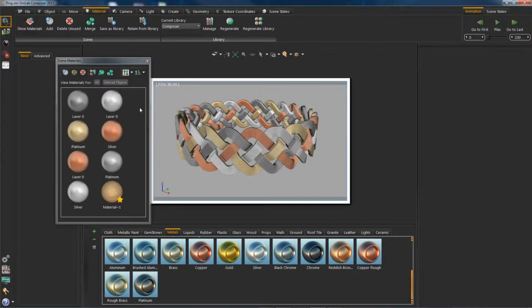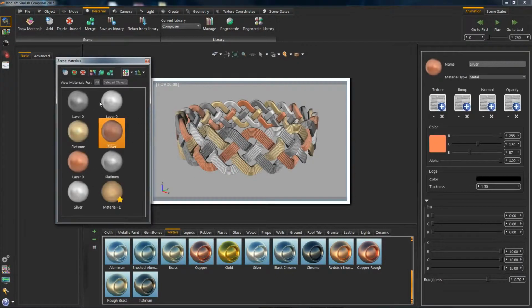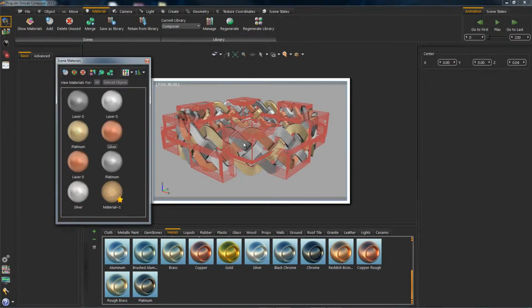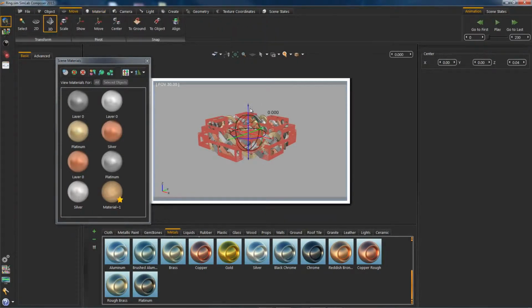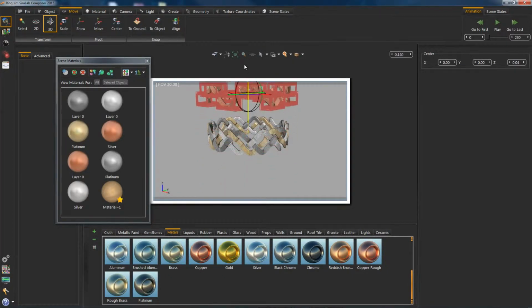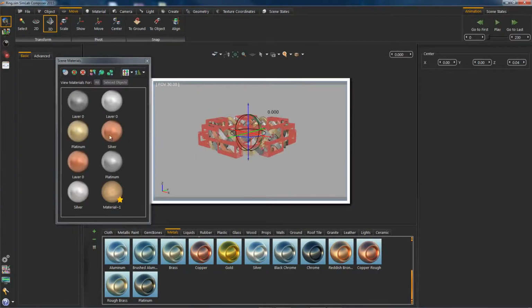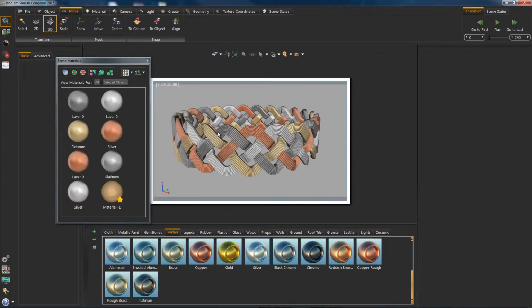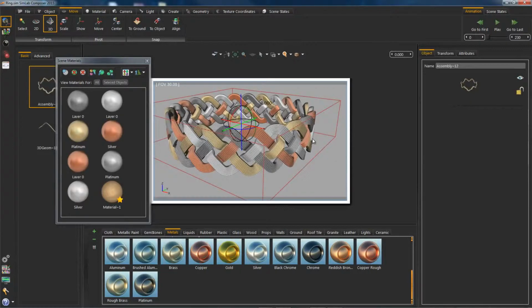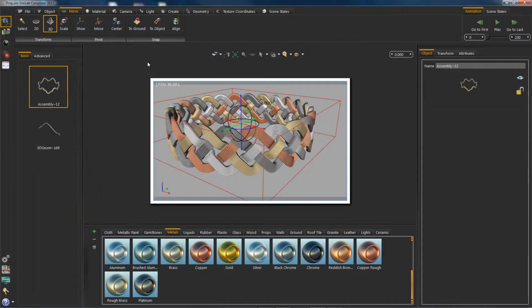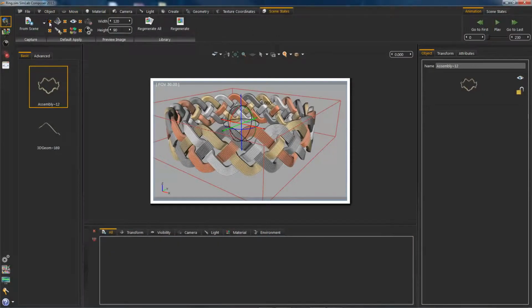So it's faster to make the selections by materials. Let's open the Scene Materials panel. Click on any slot, then click the Select Through Materials icon. As you can see, everything that falls under this material is selected and is acted on as a single body. Now, let's uncheck the Scene States filter, which we don't need. Just leave the Materials filter checked, then press the Capture icon.